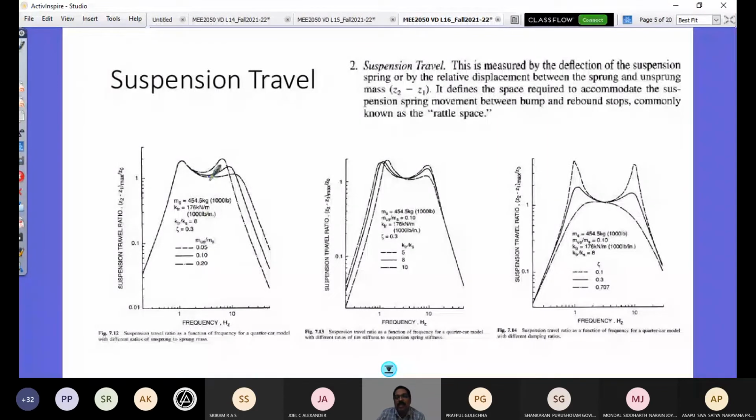Similarly, you see here spring rate, what's happening. I would prefer this range to be more, which means a softer spring, because KTR is fixed. So softer spring is preferred, this dotted line. In the lower frequency range, it is not preferred till here. But beyond the mid frequency range, it is again insignificant. So you see this is different now. And again, damping: if you look, only high damping is preferred. The low damping is not preferred at all. So the high damping value is preferred for this.